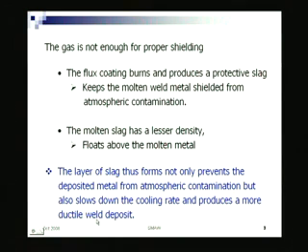Steel, if the cooling rate is very fast, that is referred to as quenching. You heat up a metal and dip it in water, it becomes hard and brittle, but if you heat it up and allow it to cool very slowly, it is annealing, right. So, somewhat that effect of annealing takes place.